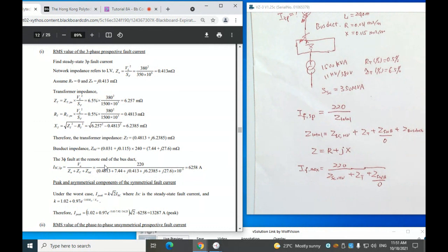That means we do not need to include the bus stop impedance in the calculation. So if we want to find out the maximum fault current, the circuit impedance is not included. We do not need to know the impedance of that particular circuit. We just want to know everything up to the origin, the beginning of the circuit.